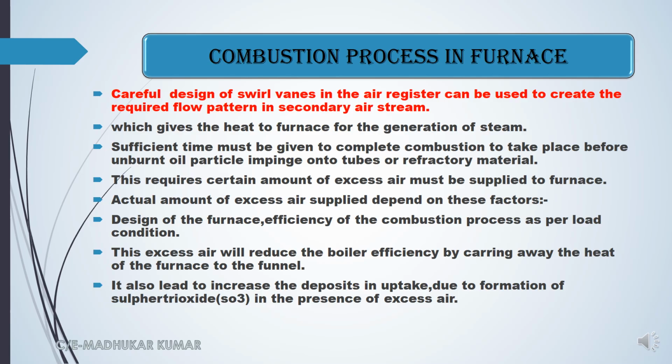But what happens if this excess air passes through? It reduces the boiler efficiency because it carries away heat from the furnace to the funnel. So the heat which should be utilized in the furnace is thrown out through the funnel to the atmosphere if the air is excessive. So the amount of excess air also has to be well calculated.